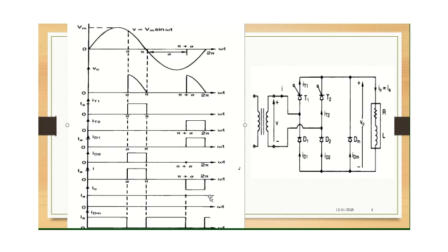So assuming that the ripple content is very negligible. Why? Assuming that again, because the load is highly inductive. When the load is highly inductive, then the time constant L/R will be high, right? So that will give a very smooth curve. So ignoring that ripple, here it is shown as a straight line. Okay, so that is about the waveforms.